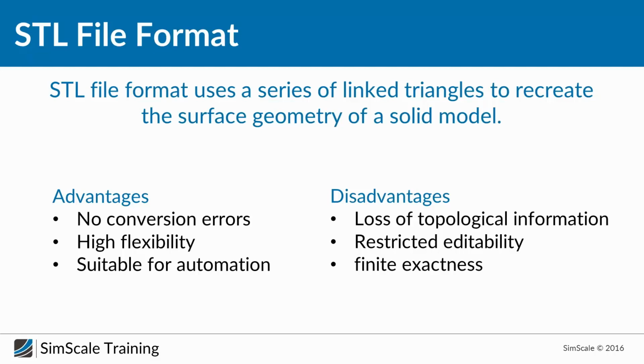But of course, nothing is perfect in this world, so we have advantages and we have disadvantages. The loss of topological information and restricted editability. When you create the STL format, you can't edit this model. You can't add, for example, a fillet or any other operation, or add more material on top of the STL. When you create the STL, you can't go back to the editing phase.